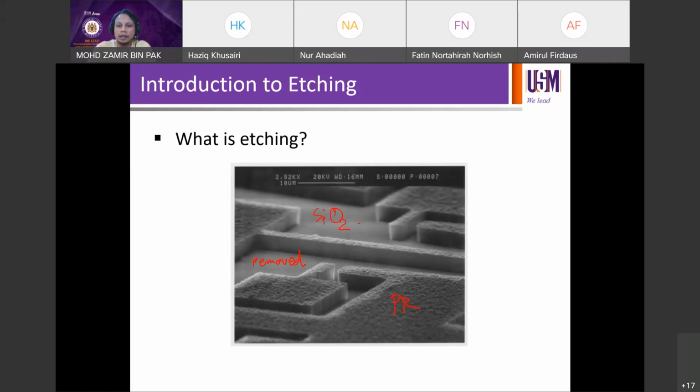Now, if you want to pattern the oxide, if you look at this, for example, the oxide is not yet patterned, right? So the oxide is just there underneath. Under the resist there is also still oxide, which is part of the other layer. So you have an oxide blanket because you've grown it through, say, thermal oxidation, and then you cover certain areas with resist. That will be a protection layer. So we will look next at how we do the etching of the open areas.